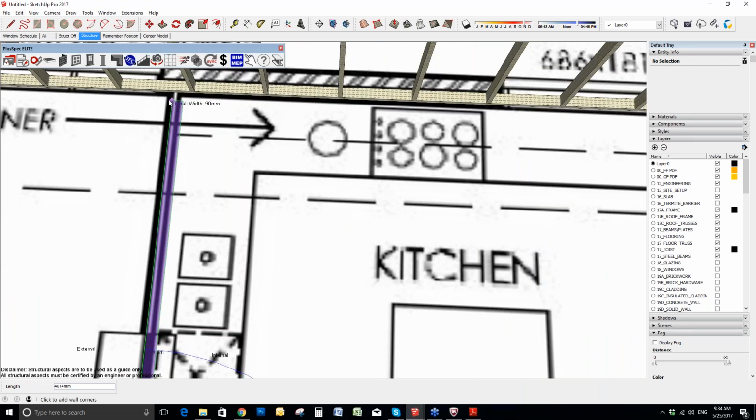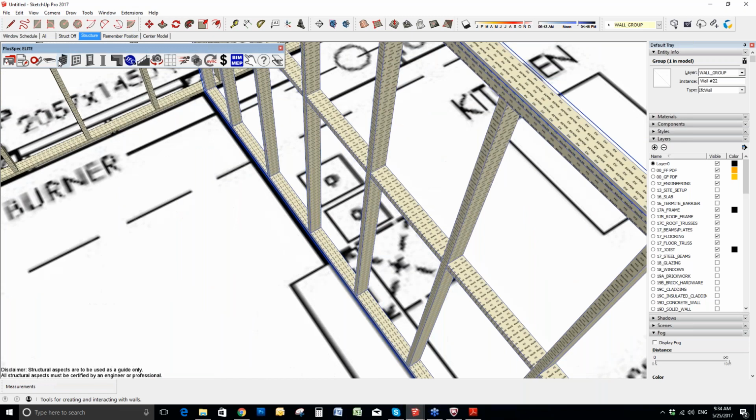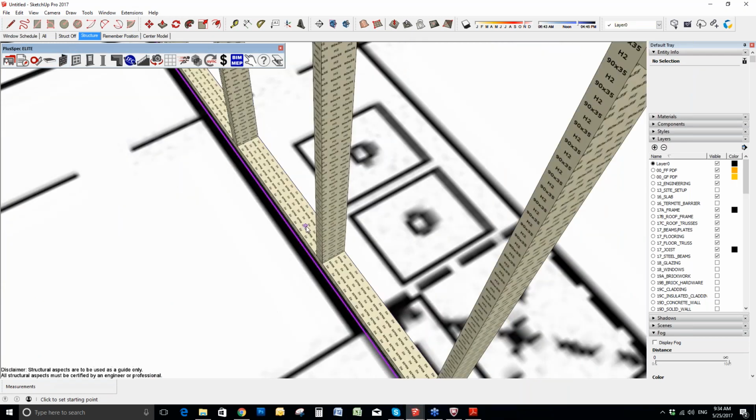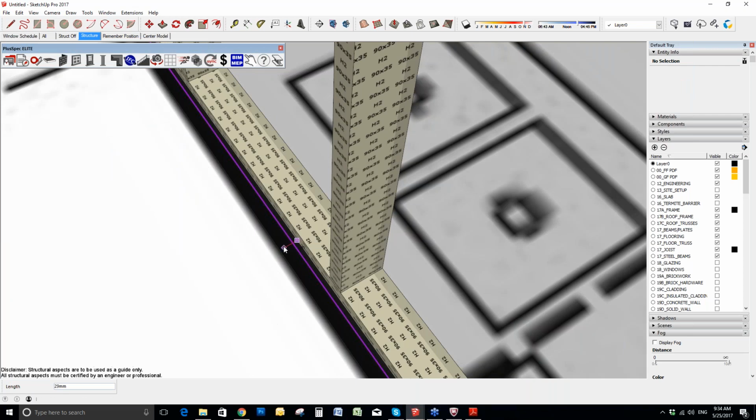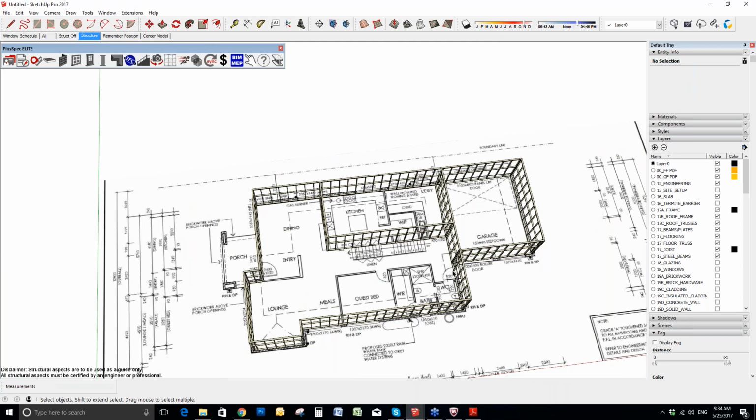and click. Now if you want to move your walls, the PlusSpec tools are easily redefined. You can go into the wall tool and you can push and pull them. So it means I can left click and move it out if I've realized I didn't place it in the right spot. Now this is an easy process. It's simply me continuously going through and adding in my walls.